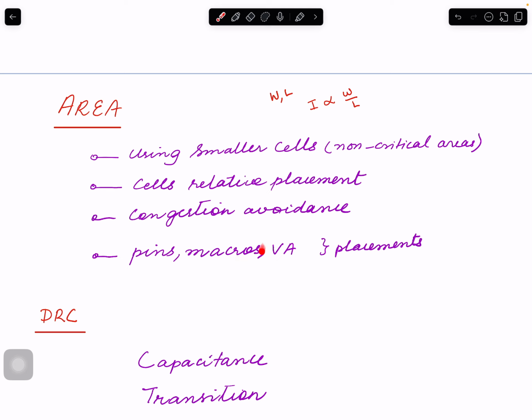Macros actually play a super important part, because macro position depends on the timing interface to macros, and that can have an impact on the area of the chip, because typically, for example, SRAMs will be pretty big compared to standard cells. So they can really constrain the area for standard cells.